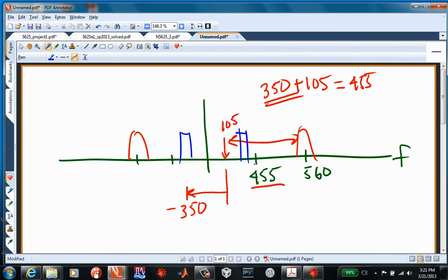I'm in favor of drawing pictures, though, because the pictures just help bring some clarity, because negative frequencies seem strange. You never think of a radio with a negative frequency part on the tuning dial. But that's my generation. The modern era is just digital tuning, and you don't think about that. But okay, this is one of those instances where it's good to draw the double-sided spectrum, because otherwise you wouldn't think that there could be a problem.